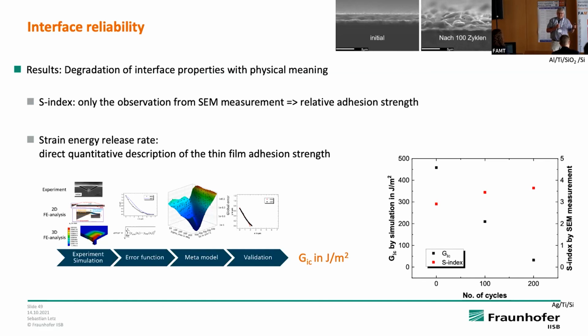And that's the downside. You need to have a power dissipation, so you need a milliwatt or maybe a tenth of a milliwatt to generate a heat rise. The heat rise you can observe maybe in the millikelvin regime, even though you are at room temperature. You see it at 2-3 millikelvin, but this is due to the lock-in technology. So if you want to have more resolution, you have to measure longer.